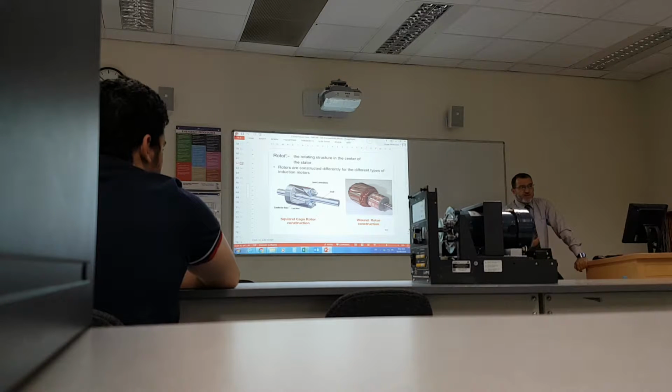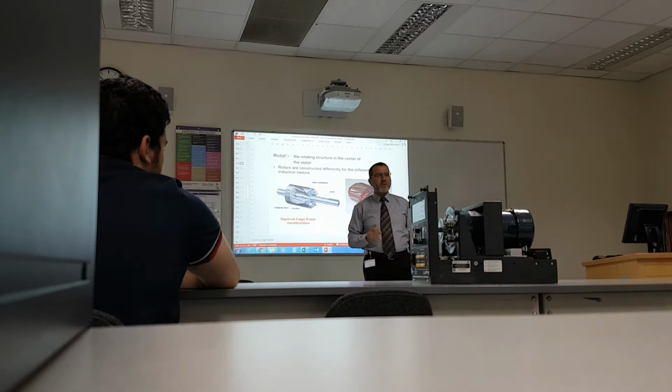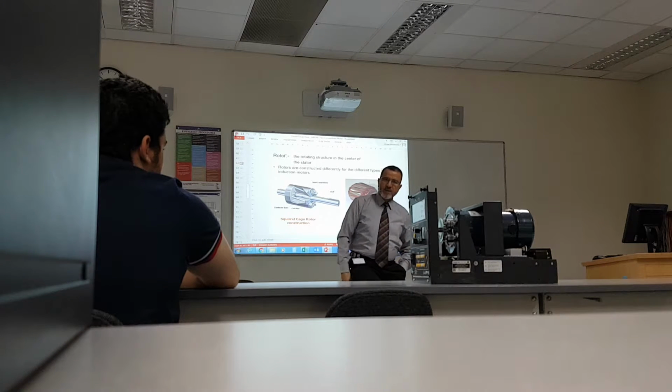Is it worth it to pay the extra cost to have more variable control on the power factor correction, or are we okay to run with just aiming for 0.9, for example? In the worst case, we're going to get 0.85, satisfy Kahrama. In the best case, we're going to get maybe close to 1. You never get close to 1, you don't want to be close to 1.